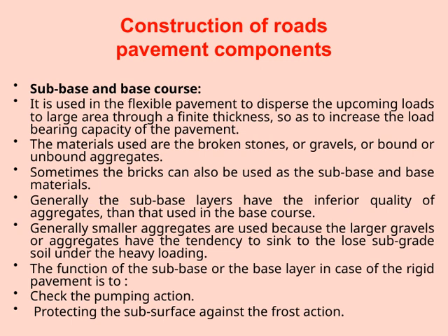In the case of rigid pavements, the functions of the subbase and base layers become even more critical. They help check the pumping action, which is the upward movement of fines or water under repeated loading, and they also protect the subsurface from frost action, which can cause significant damage during cold weather.